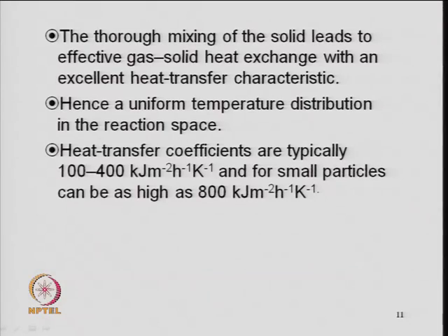and the heat transfer coefficient will be very high. If you look at the order of magnitude, it is 100 to 400 kilojoule per meter square per hour Kelvin, and for small particles it can be as high as 800, because it will depend on the particle size. Surface area per unit volume is very important, when you write H A delta T for heat transfer, or when you calculate the heat transfer coefficient. So, this will be higher in the case of fluid bed reactor. So, that is the advantage. So, when the reaction is exothermic, the fluid bed reactor can be preferred, because one can dissipate the heat and heat removal is faster.